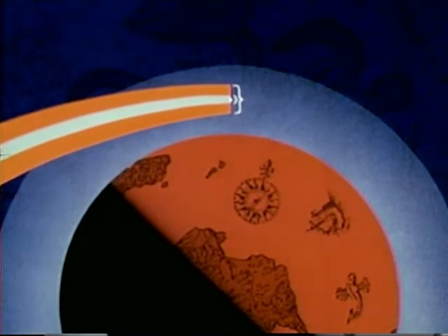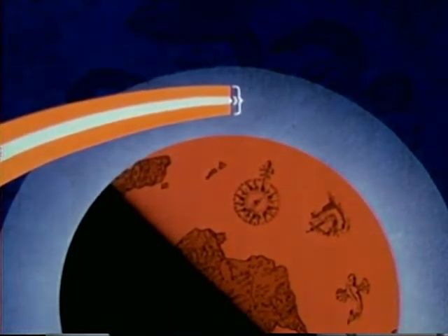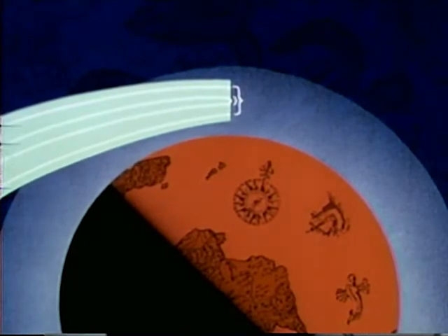However, with the limitations of hardware and trajectory design over translunar distances and velocities, it is impossible to control the trajectory to guarantee an approach closer than this to the nominal vacuum perigee altitude. Since this is directly related to the entry corridor, it can be seen that if atmospheric drag alone is used as a controlling factor, it is impossible to guarantee a safe entry. Therefore, aerodynamic lift is used to assist the drag force and widen the corridor to acceptable limits.